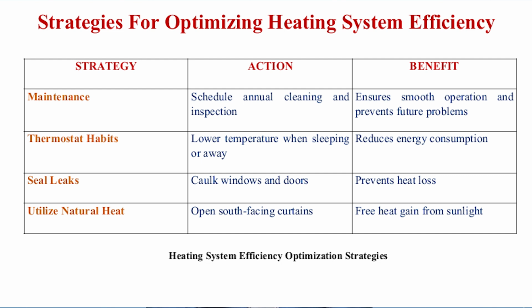Next point is seal the leaks. Like we have learned, inspect windows and doors for gaps. Look for air leaks around your frames and use weather stripping to seal them. Consider window treatments. Install thick curtains or blinds on windows as an extra layer of insulation.